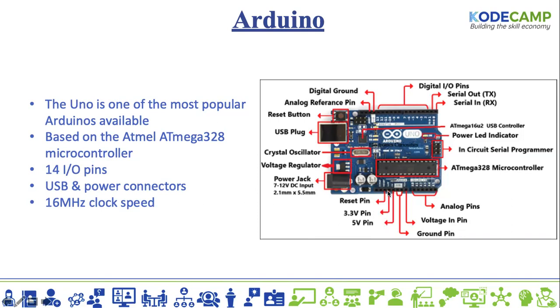I think one of the components that basically uses 3.3 volts is the NRF. NRF is a transceiver that uses 3.3 volts, and also ESP. ESP also uses 3.3 volts. We are going to talk more about that later on. So every other peripheral that doesn't use 3.3 volts, you can send 5 volts to it.